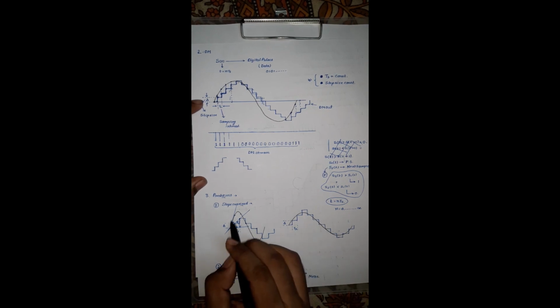If the signal slope is almost 0, it means the signal is not varying too much, or the signal is almost constant. For a constant value signal, continuous pulses are produced in delta modulation. This is called noise. Due to a fast varying signal, slope overloads are produced. And due to the constant part of a signal, granular noise is produced. These are the two major disadvantages of delta modulation.